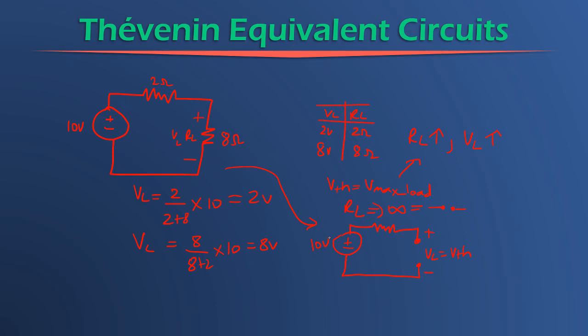Surely it must be, because I've got a 10 volt source there, and the voltage here is 0 volts. It will increase by 10 volts. That will be sitting on positive 10 volts there. The voltage drop across this resistor must be 0 volts because the current flowing through here is 0. That means the voltage at this point will still be 10 volts.